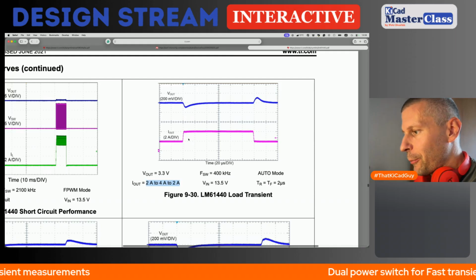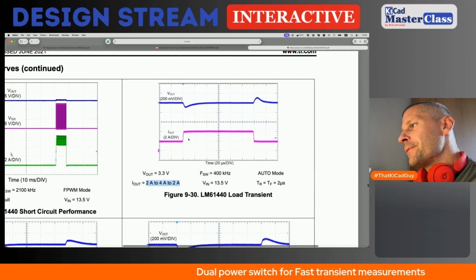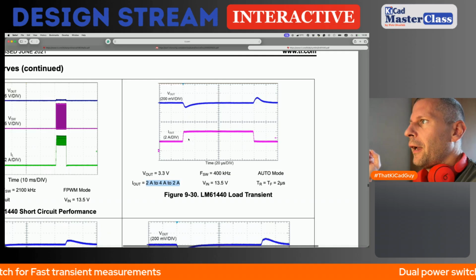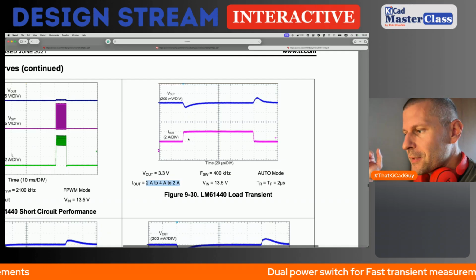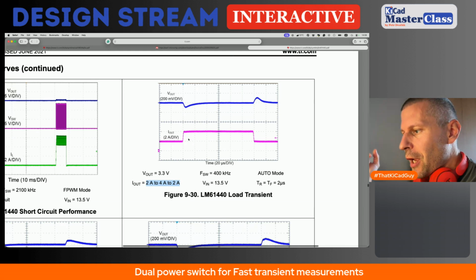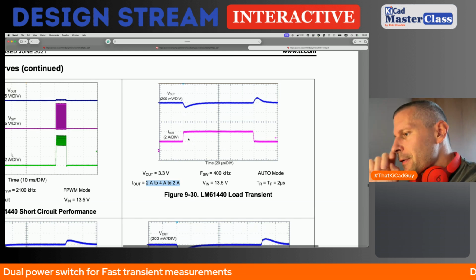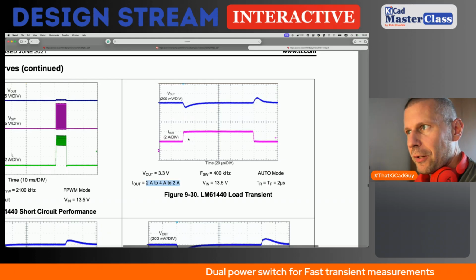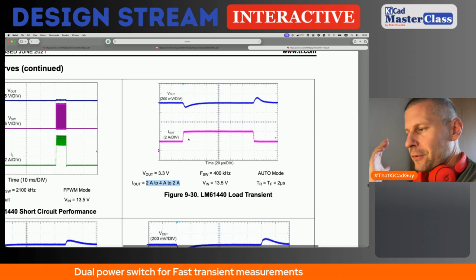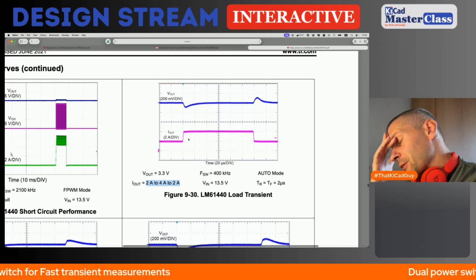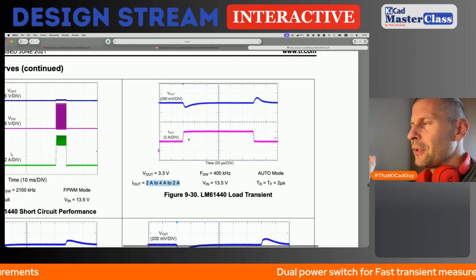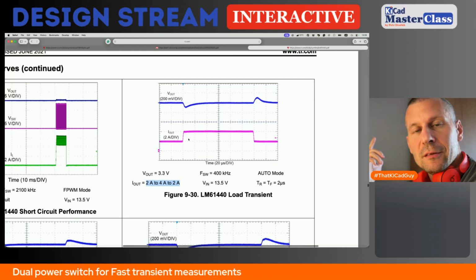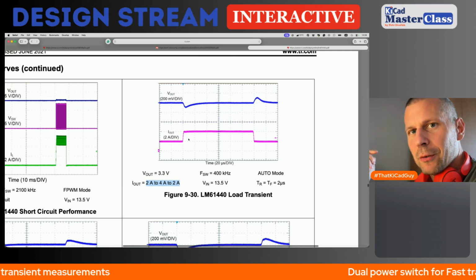There is a feed-forward capacitor in the voltage divider, so we can compensate the feedback network, and many things basically can be changed on the PCB, like the number of output capacitors, the type of output capacitors, the feedback voltage divider, as I said, the capacitor, the feedback divider to provide some compensation to the feedback for the error amplifier, etc., etc. But I need the highest quality possible power switch.